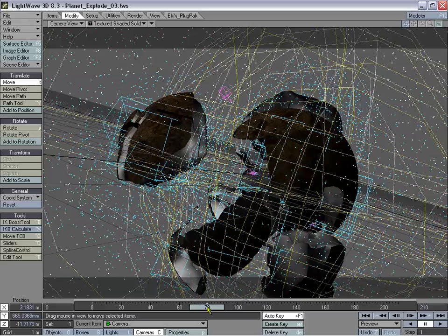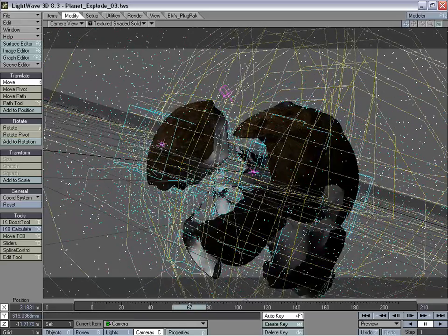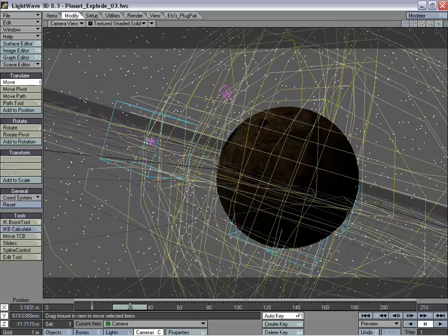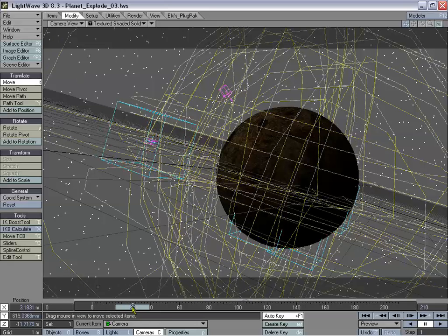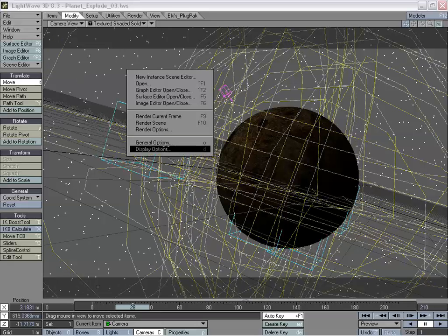And pretty much what that means is when you're doing your render, if you adjust the film grain to the point where you have too much and you want to reduce it, then you're going to have to go and re-render the entire animation. So what I would suggest doing is actually when you do a render, render it out as images.